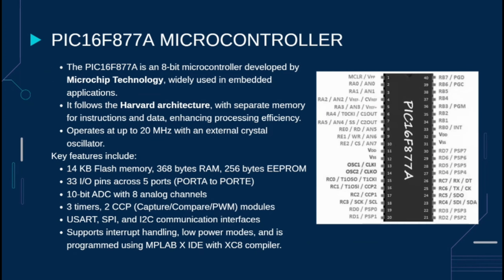So this project is built around the PIC16F877A, an 8-bit microcontroller from Microchip Technology. It uses the Harvard architecture, which separates program and data memory, allowing faster execution. So here are some of its key features. 14 kilobytes of flash memory for program storage, 368 bytes of RAM, and 256 bytes of EEPROM.